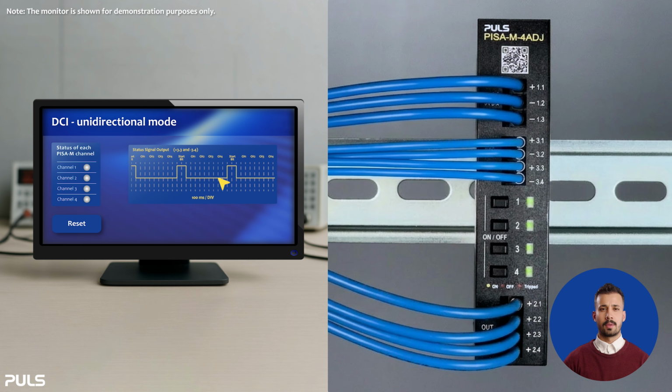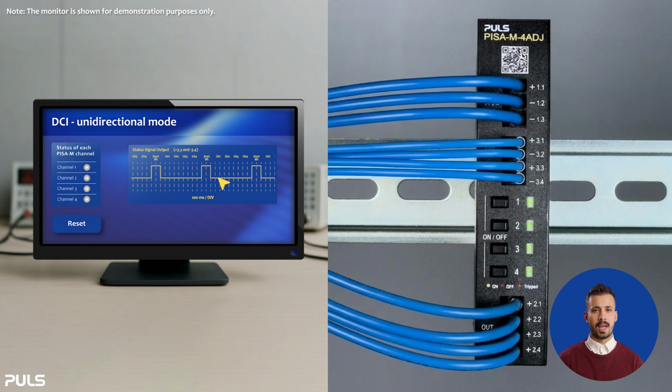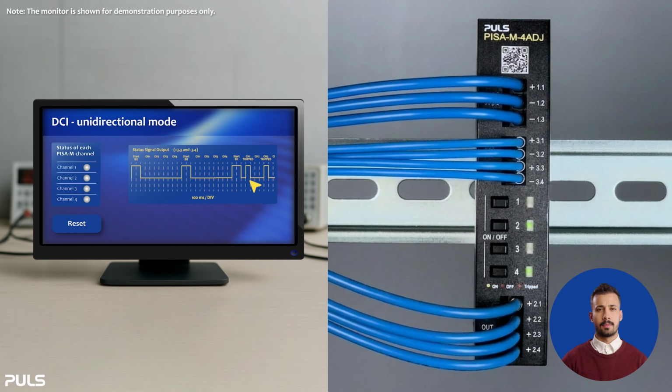For the signal coming from the PISA-M, each sequence begins with a 200 millisecond start bit, followed by a 100 millisecond pause, and continues by the channel information, and then repeats continuously. The timing here is 100 millisecond per bit, plus a 100 millisecond pause, with a total sequence length of 1100 millisecond. If a channel trips, the corresponding status indicator starts flashing red, and the bit sequence changes accordingly. So for example, if channel 1 and channel 3 trip, this can be seen both in the channel indicator lamps and in the bit sequence running on the screen.